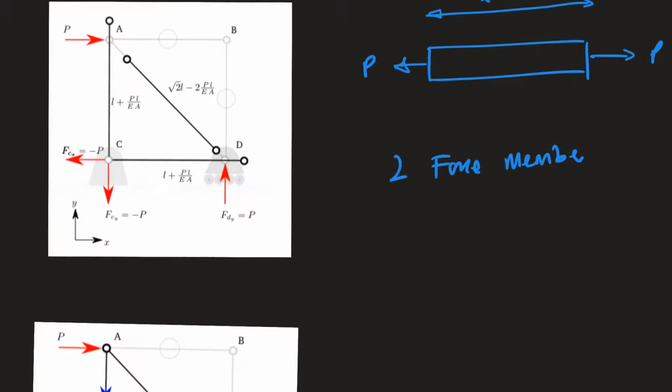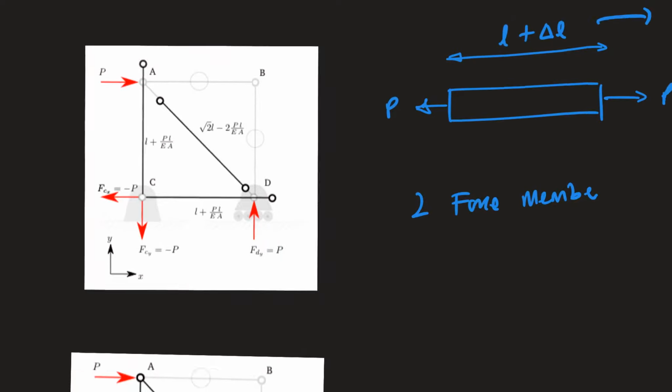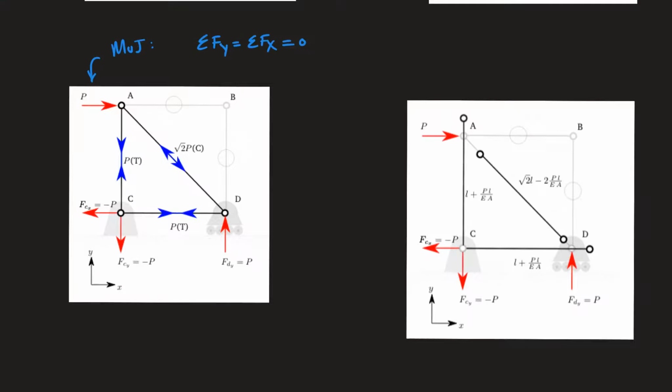Okay, so for here, we can then work out the length of all of these members. So the one on the bottom is under tension. I've drawn those as arrows going towards each other. The one at the top is under compression, and these are under tension. So we know that when we've got a tensile force, members AC and members AD must be getting longer. Okay, sometimes confusing because the arrows are going in the direction of the internal force there, but these are going to extend, and this one is going to contract.